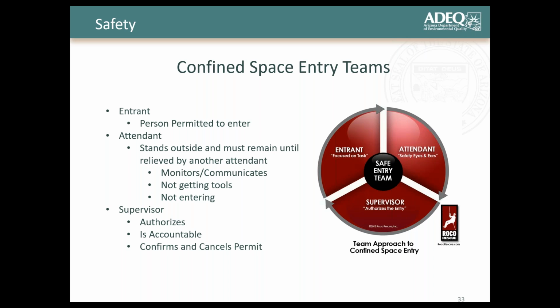You also have supervisors. A supervisor is not necessarily a supervisor by title, but a supervisor in the confined space entry team. This is a person that authorizes the entry, that is accountable, right? That confirms and cancels the permit. Any trained personnel can be considered a supervisor in a confined space as long as they are defined in that role.